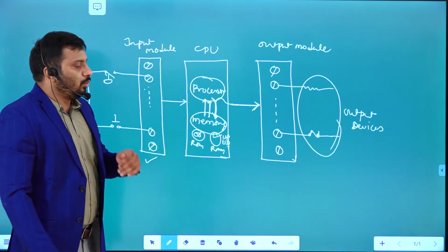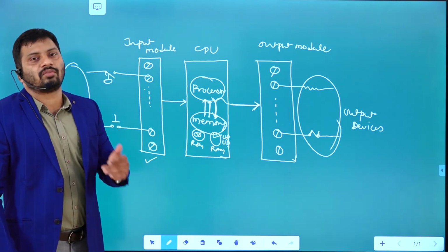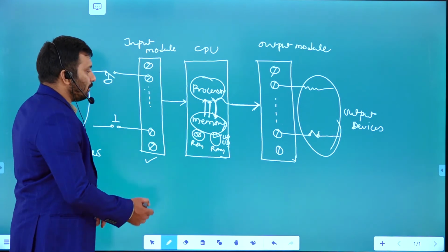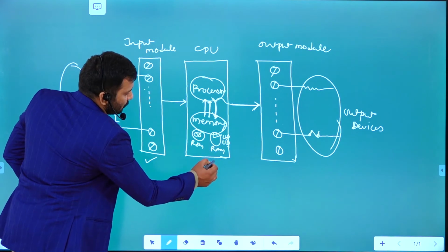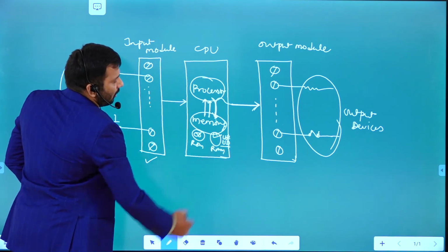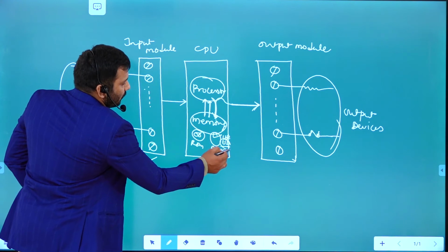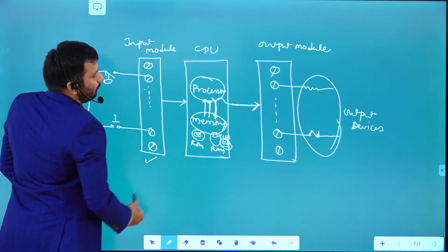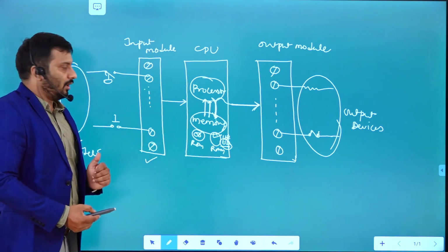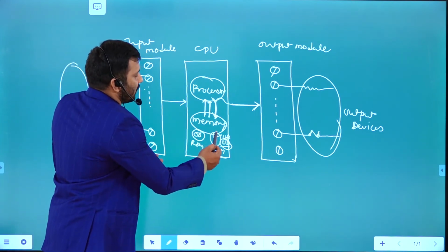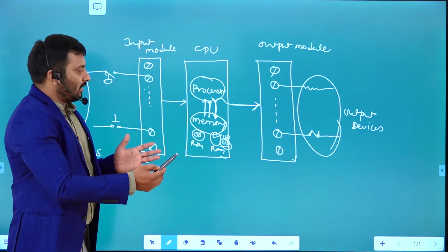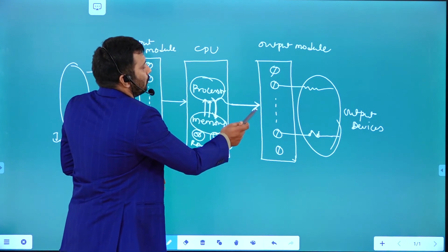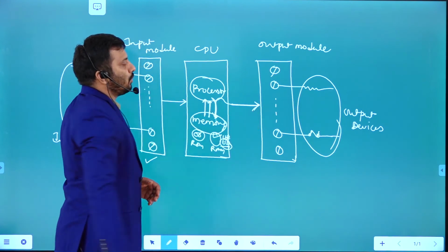Now we have to look into the software part, a little bit, to write a program for this application. RAM is used to store the user data and user program. You already know how user data comes from the input switches and is stored in memory as the input scan block. After some operation, the updated output data is also stored in the output image table to be sent out through the output module to control the output device.